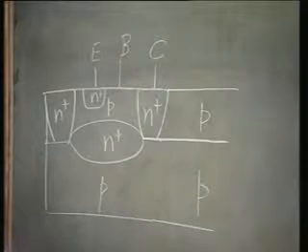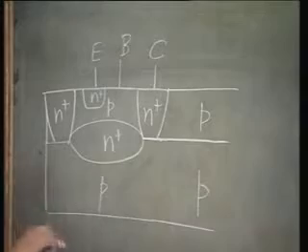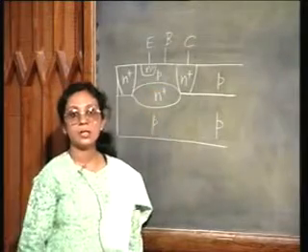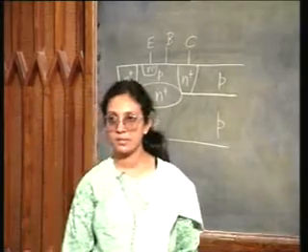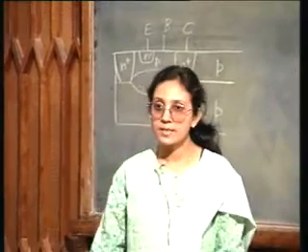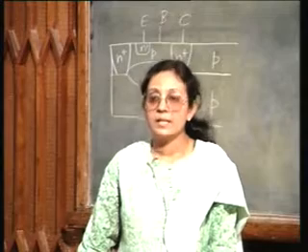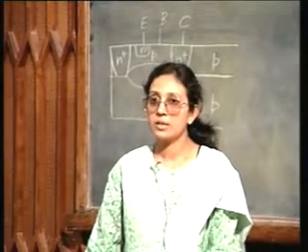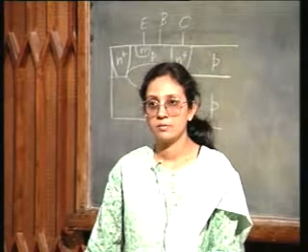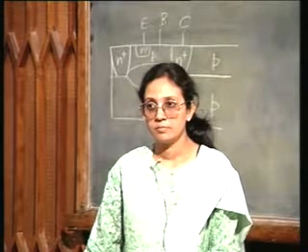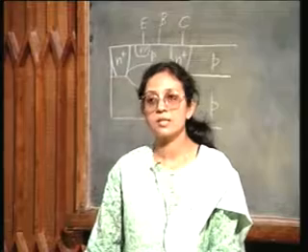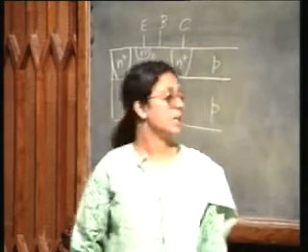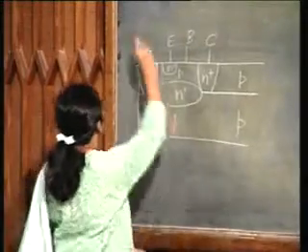Okay, that is, each transistor is surrounded by an N plus region, by this N plus P. Now, collector is N plus. I have N plus collector throughout, and this collector substrate junction is isolating the two adjacent devices. The reverse biased collector substrate junction is creating the isolation. So, you see this is called collector diffusion isolation.